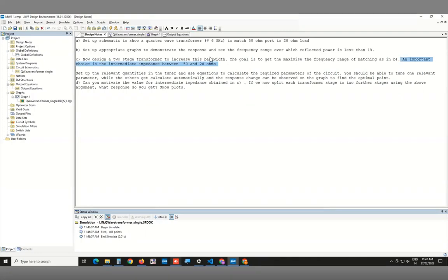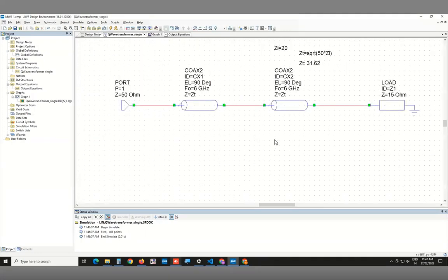Right? So because in this circuit, now you have ZT, which I should really change now, because these two impedance transformers' characteristic impedance will not be the same because they're transforming different pairs of impedance. So I need to define ZT1 and ZT2 for the two variables here. ZT1 as before is for the first one, but now the question is, how should we define that value?